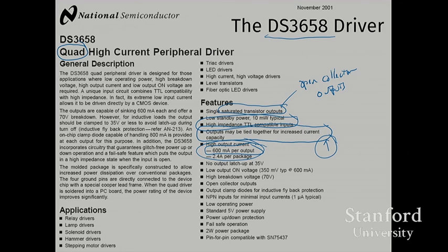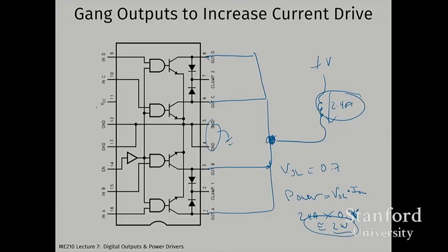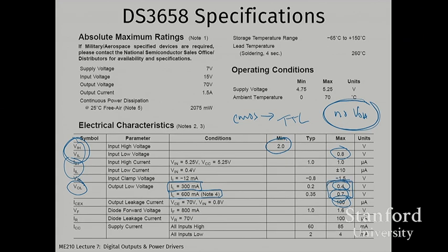No, it doesn't. So if you run this thing too hot, it might actually fail. And this is something you need to be concerned about if you're fooling around and not keeping track of your total currents. In the way we're going to compare a lot of these devices, we're going to look at this spec, the voltage in the output low state. We want those to be low, because the lower they are, the less power we're wasting cooking the chip, and that saves more power for turning the motor. So that's the baseline comparison from one to the next: how low is that output low voltage.